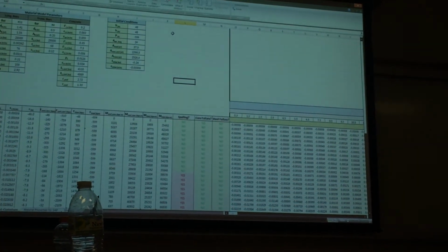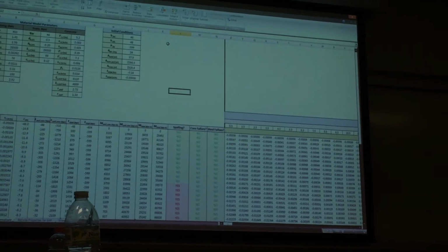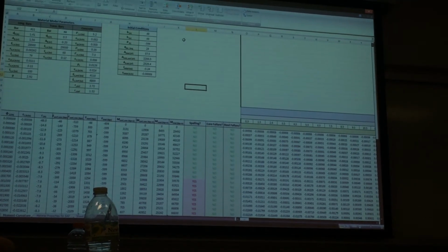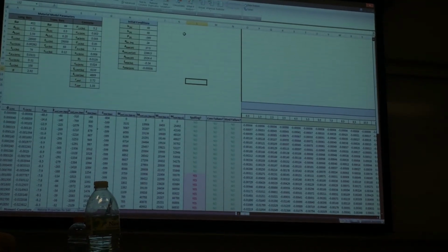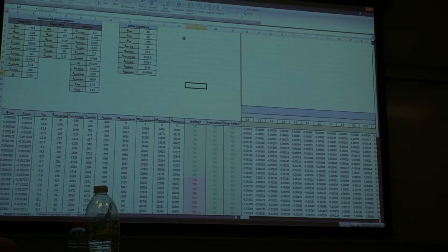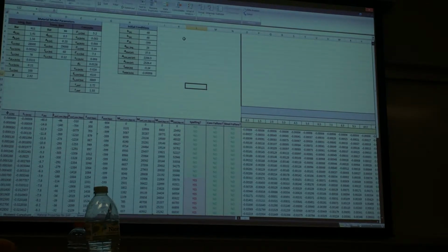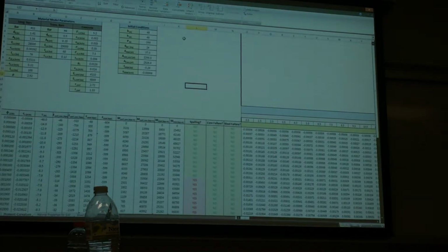And you can do the same thing for, let's say, initial bending moments on the cross section. So your bending moment would be MC over I, and there's transformed I as well. So you have, let's say, the I from your concrete, but you also have the I from your steel, and you can transform that I to be an equivalent I. And ACI details all that stuff in detail for kind of methods for doing that. But that's more like a reinforced concrete sort of thing I'd cover, not so much here.